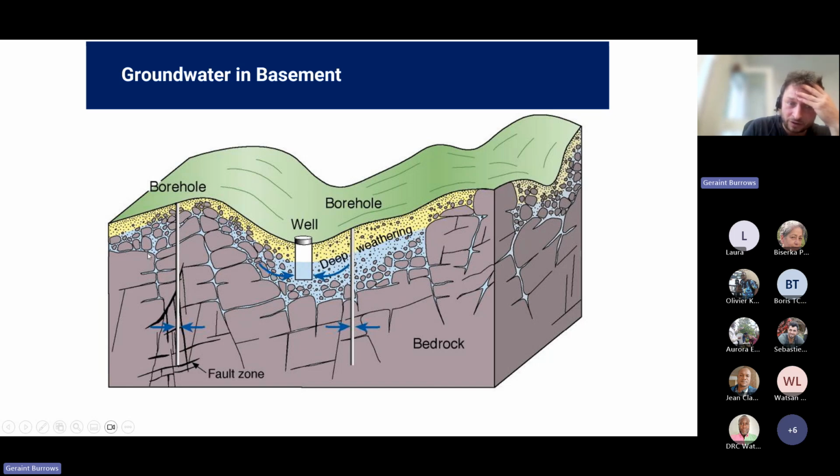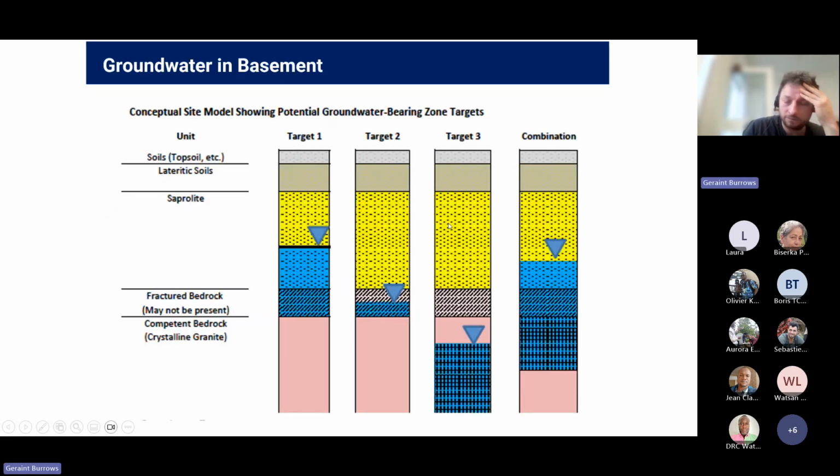You can see that would impact a profile with a constant separation traverse: you'll have higher resistivities here, then they'll reduce and drop down at this point, before increasing again as you go back into the hard rock, moving your profile from A to B.